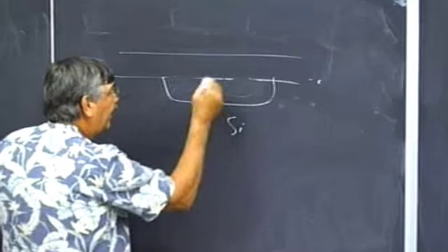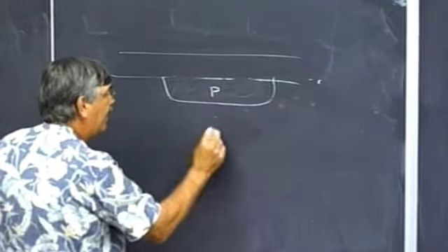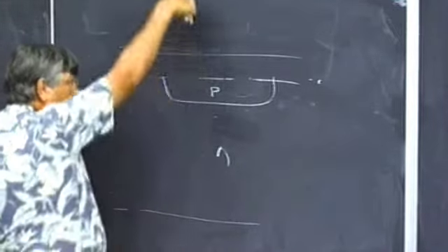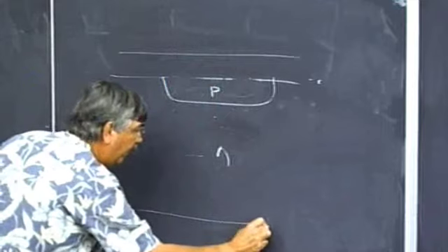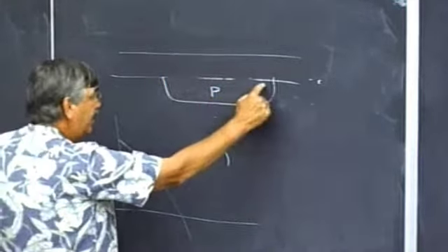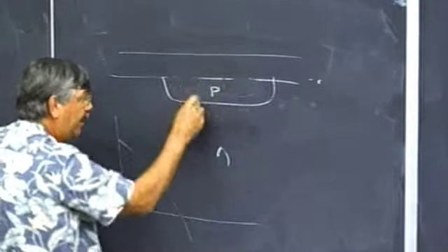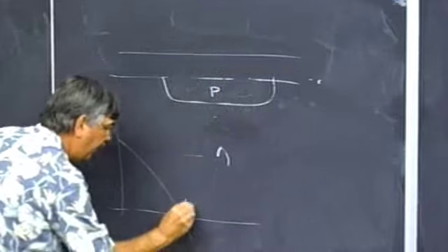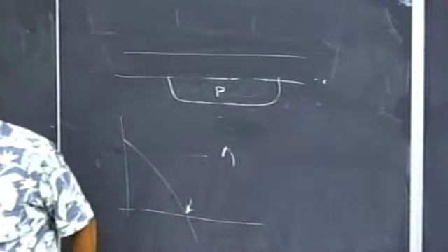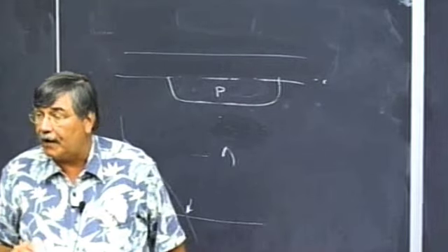So if this was, for example, acceptor dopants, then we would have p-type material in an n-type region. The n-type doping, as we come down from the surface, would be relatively small, and the p-type doping would be higher. It would be highest at the surface, that's where it came from, and it would have diffused down this gradient. Where the two are equal is the junction. And we repeat many, many times in many, many different places. All right? So that's the basic photolithographic process.